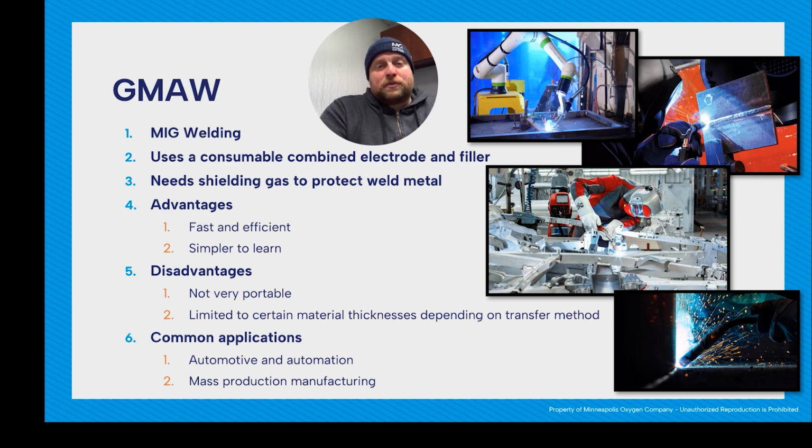Great example is short circuit. That's the transfer method that is most commonly used, I would say, with GMAW. Not really suggested for much over like 1/8 of an inch if you're doing structural steel. I know most things say don't really use it over 3/16. It's definitely for a thinner type of metal or a heavily prepared weld joint.